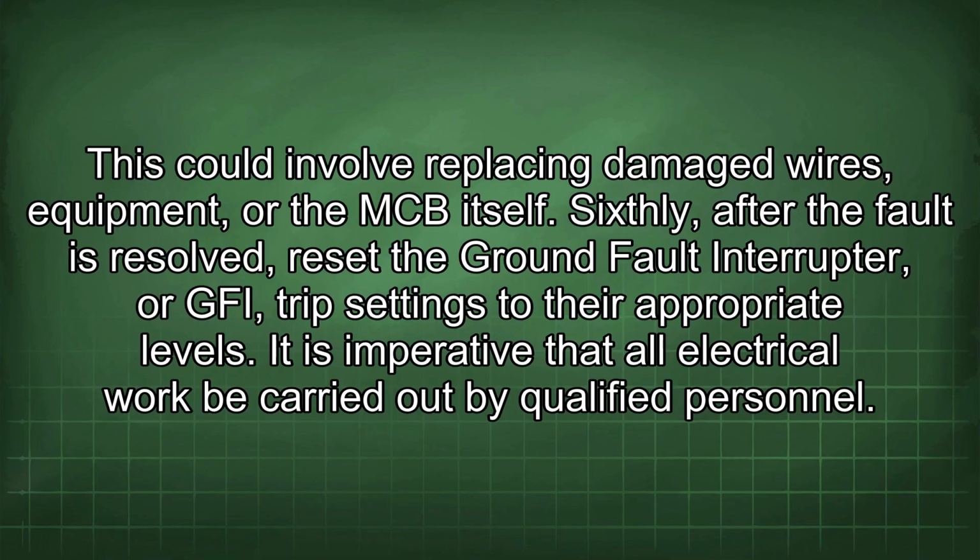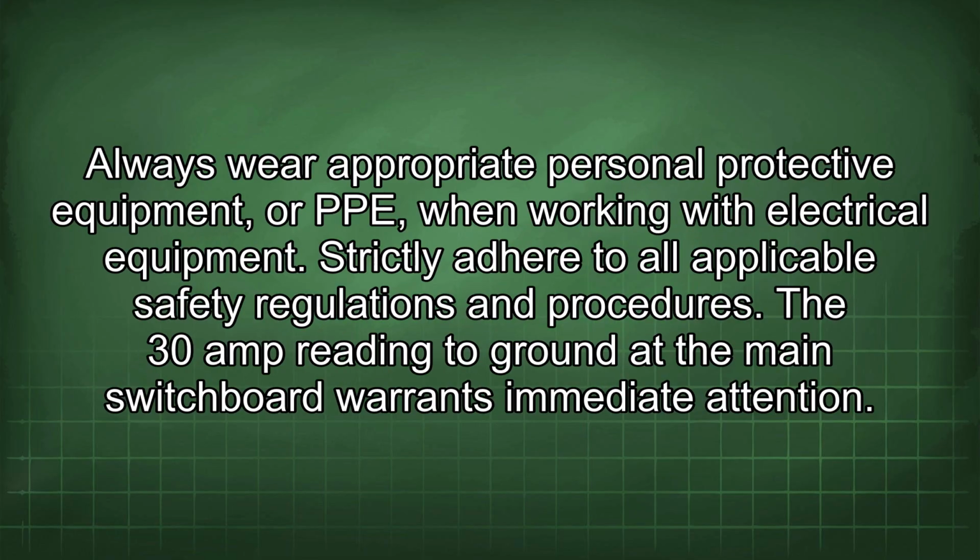Sixthly, after the fault is resolved, reset the ground fault interrupter, or GFI, trip settings to their appropriate levels. It is imperative that all electrical work be carried out by qualified personnel. Always wear appropriate personal protective equipment, or PPE, when working with electrical equipment. Strictly adhere to all applicable safety regulations and procedures.